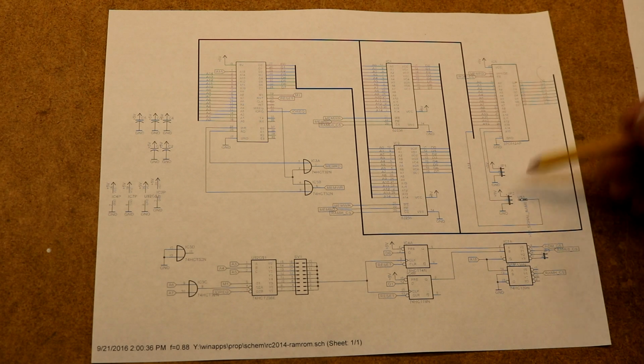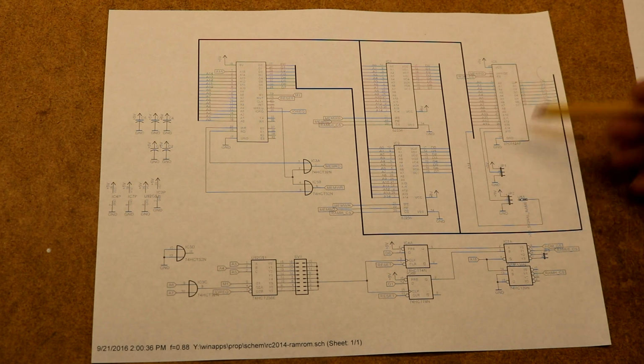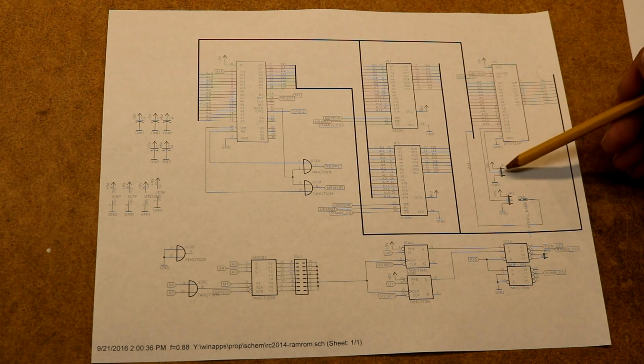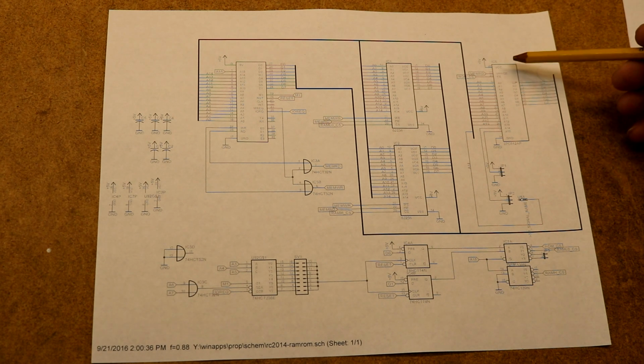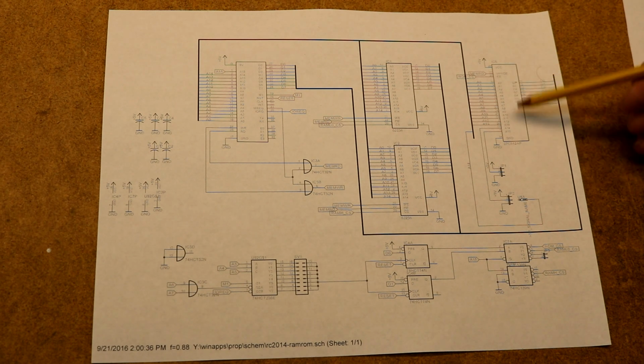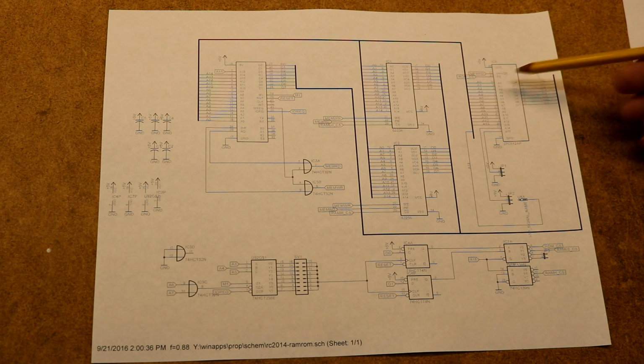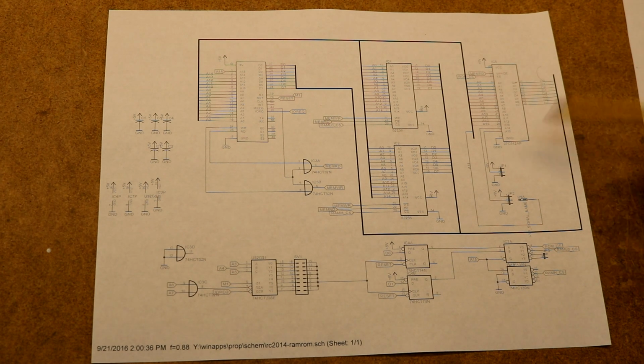And then there's a couple jumpers down here which let you select which 16K window you want out of this ROM. So you could segment this ROM into 4 pieces and have 4 different bootloaders in it, and then jumper into whichever bootloader you want. And I do that. For example, one of them I run the CPM monitor, the other is BASIC, and the other's a switcher for my bus supervisor board. So it's nice to be able to run 4 different things in the EEPROM.